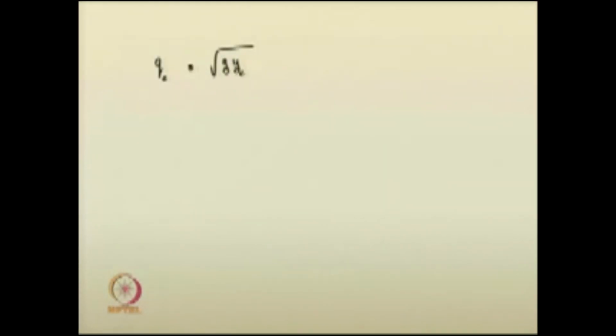We have already suggested that this is equal to root of g y c cubed, or if energy is given, for a rectangular channel this is root of 8 g E cubed by 27.